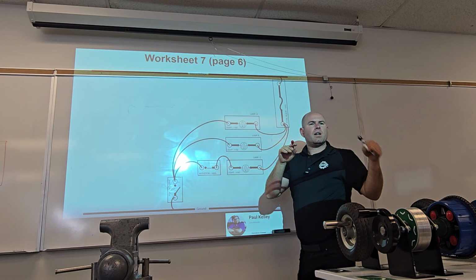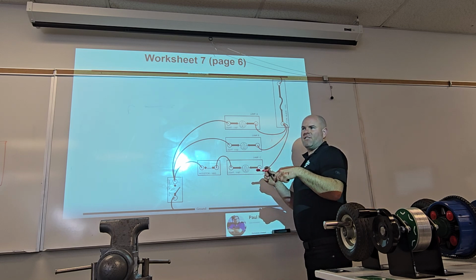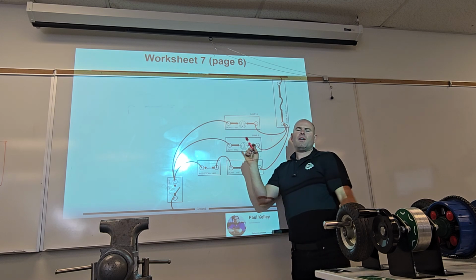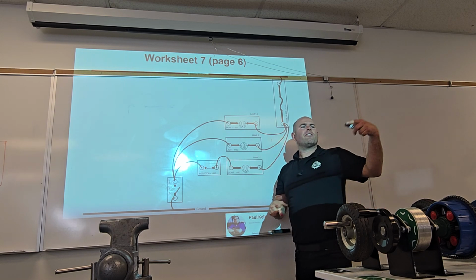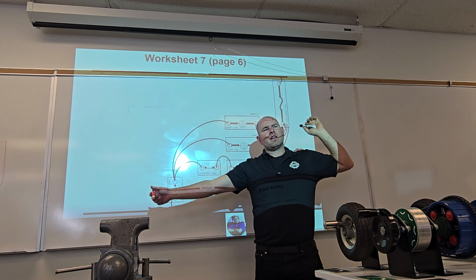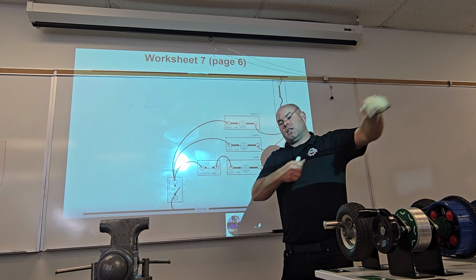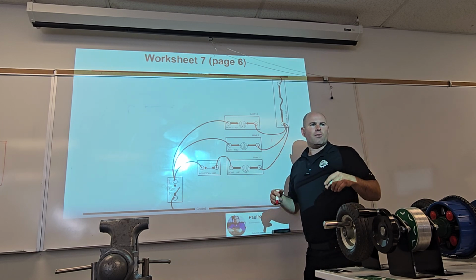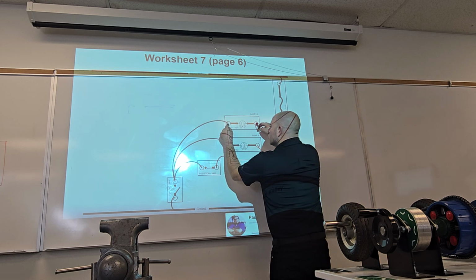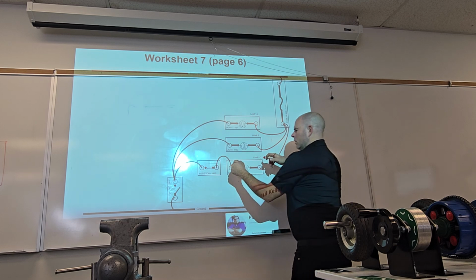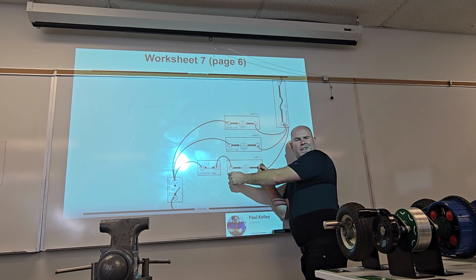So like 2 different ways to go about the problem. If it's on the circuit board, available is pretty nice and convenient because you can do it quick. If it's on the car and it's hard to find a ground and you're testing a brake light and you're not wanting to put your black lead on the battery and then stretch and stretch, your leads are too short, you might just go to the brake light itself and be like, let me just check the bulb. Boom. It's dropping 12. Boom. It's dropping 12. It's dropping 0.1. That's not good. Make sense?